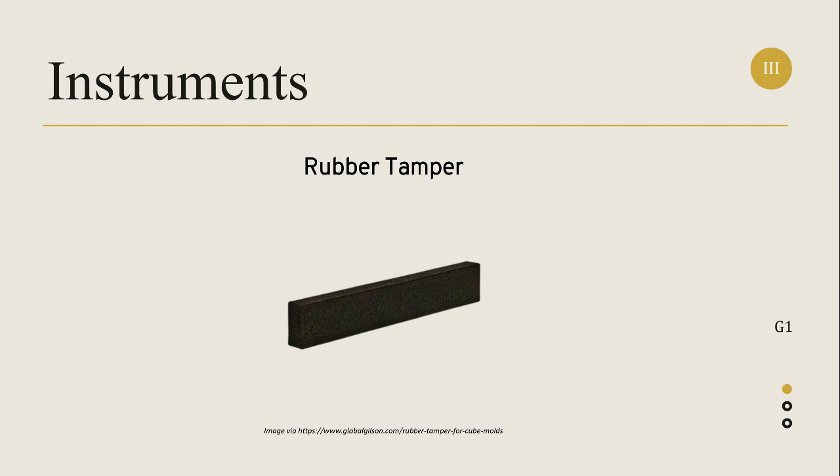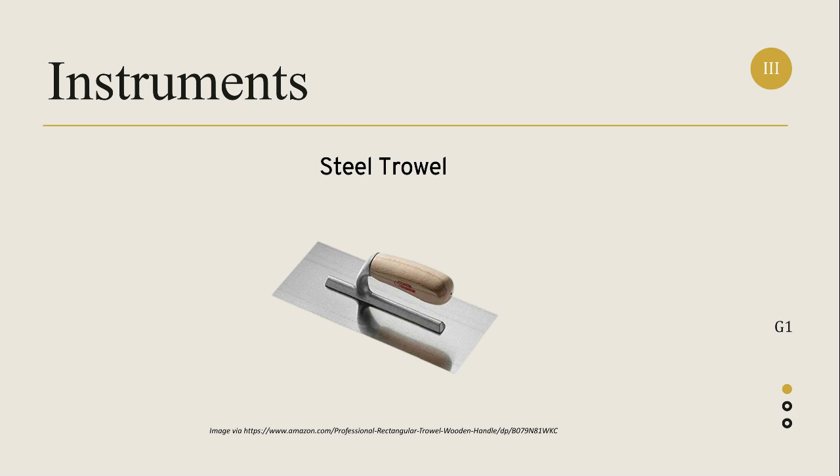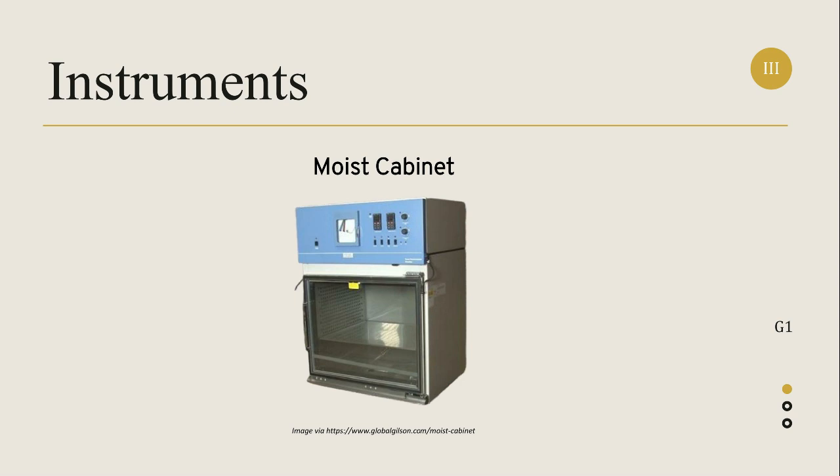months. Next is the trowel, having a steel blade 4 to 6 inches in length with straight edges, used for digging, applying, smoothing, or moving small amounts of viscous or particulate material. Next is the moist cabinet for curing mortar and concrete test specimens, which has 11 square feet capacity and is heated, with a triple pane glass door to minimize condensation for observing specimens, conforming to the requirements of specification C511.